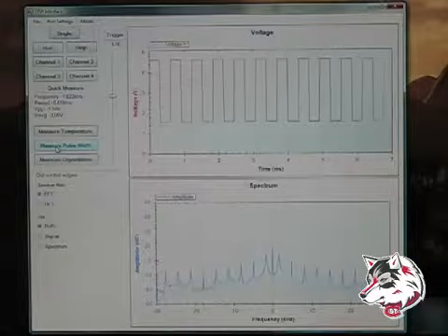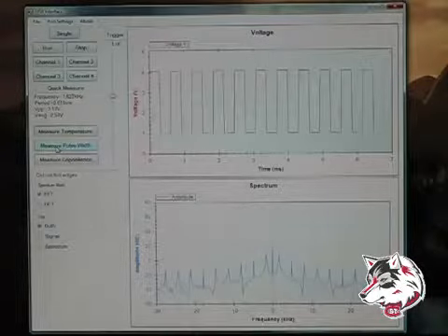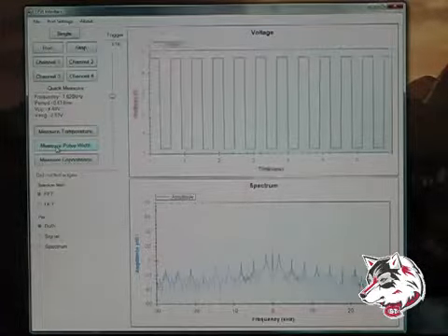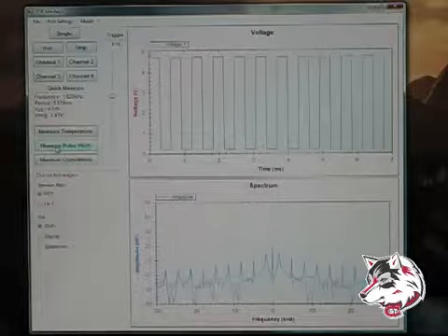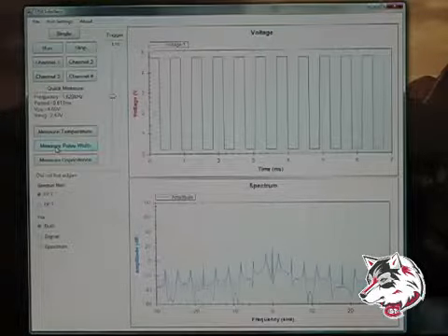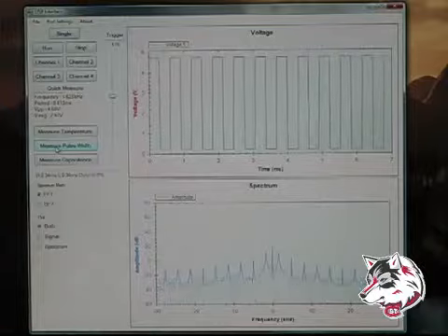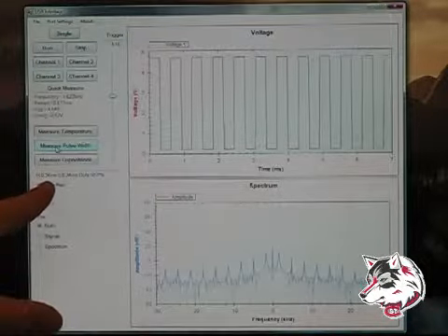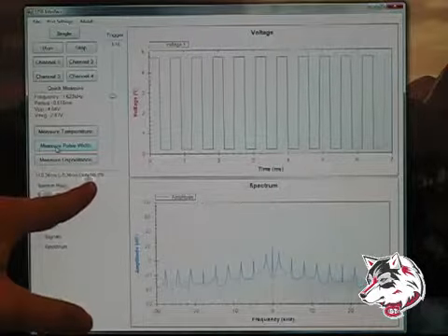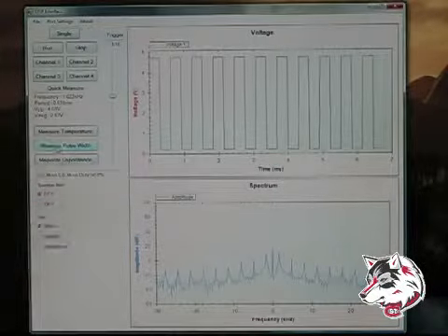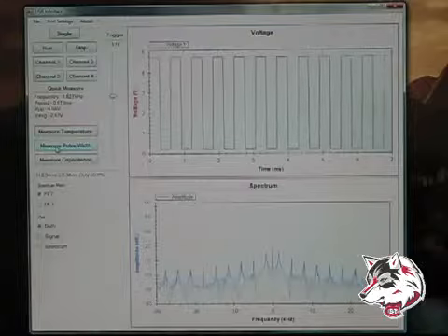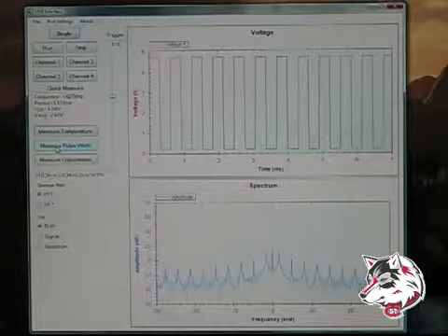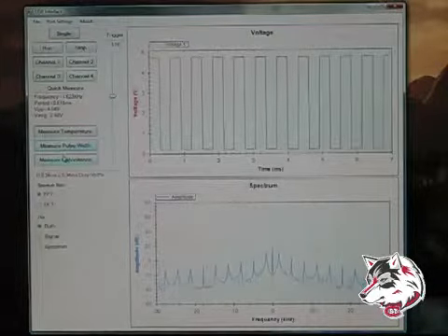And since we messed around with the offsets, we got to get it back down. Right now this is going to use the compare and capture mode and find a rising edge and falling edge based on logic 1 and 0. So it has to make sure to go above and below that. So now we're above and below that. You see we got 0.34 milliseconds, 0.34 milliseconds, and a duty cycle of 50%, what we expect. Unfortunately, this is an older function generator. I can't change the duty cycle, but trust me, it works just fine.